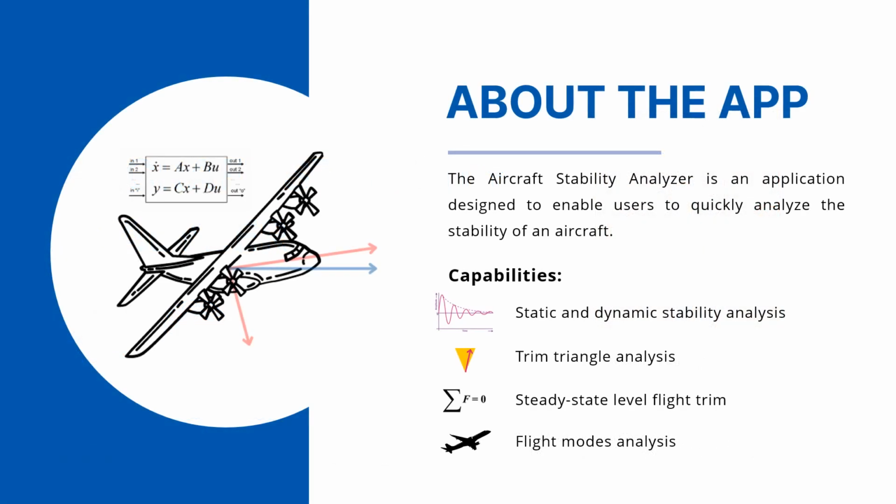This app enables users to interactively analyze the dynamics and stability of an aircraft. It offers four main functions: static stability analysis, trim triangle analysis, aircraft model trimming using a Simulink model, and a flight mode analysis using poles obtained from the linearized equation of motion.